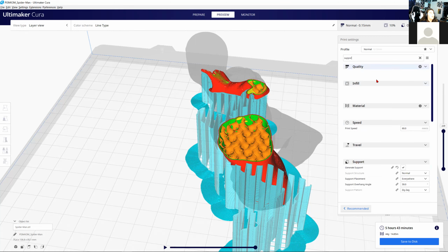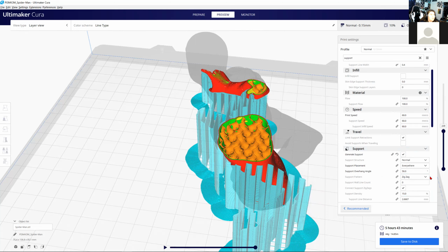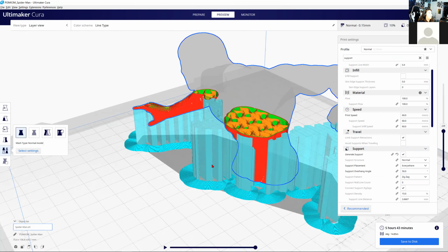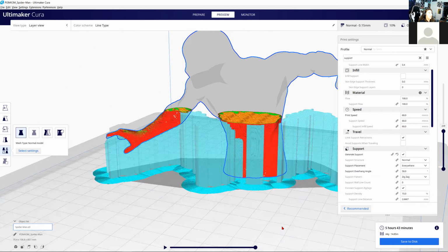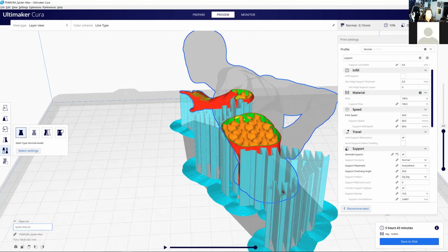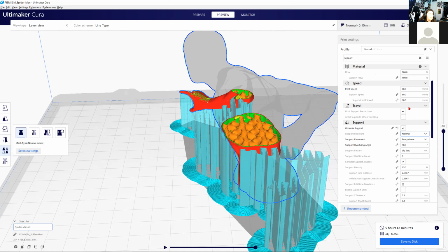You can also, just like with infill, change the type. So here, support pattern, you can do zigzag lines, gyroid. I usually just use zigzags because they're a little easier to take off for me personally. Usually how I take them off is I grab the starter point, and if I just pull, they all come off pretty nicely, since you kind of stretch them and they just move. But sometimes if it's surrounding the whole build, it's a little harder to do.